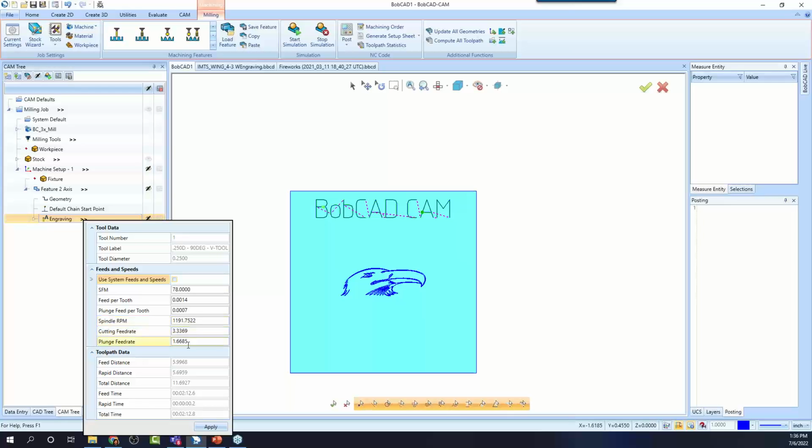I think there's probably two different workflows here. One, maybe you set the tooling and speeds and feeds first, and then you apply the operation. The other one would be where you set up the geometry and the operation in the toolpath settings, and then you go back and adjust for the specific tool that you might be using. Either scenario, when you're done with a project, you post the code and you're ready to run on the machine and it ran well. That's a process, and you should save that, store it, and reuse it. And that's where these CAM tree templates come in really helpful.